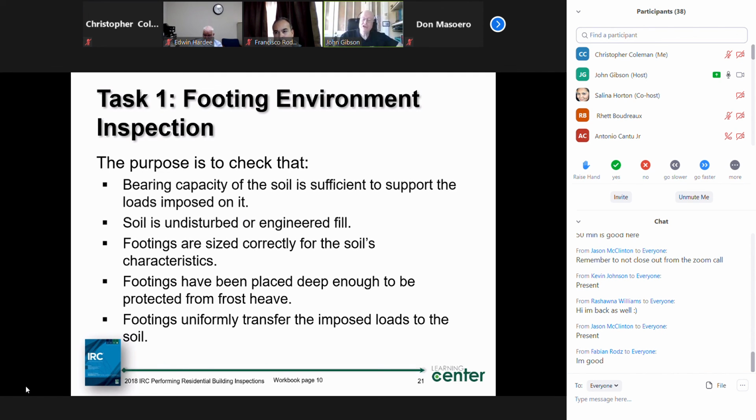Now, we traditionally run into, and I'm going to go over that in a few minutes, conditions foundation wise, footing wise, where maybe my soil profile doesn't meet that 1,500 pounds per square foot. So that means I can't use the footings that are in the IRC. Well, that means I need to get an engineer or an architect, a design professional, in other words, to design that.